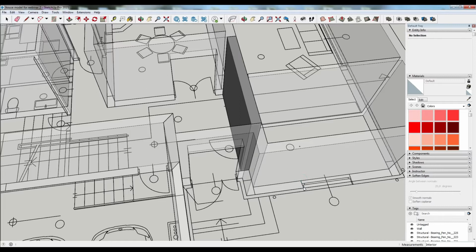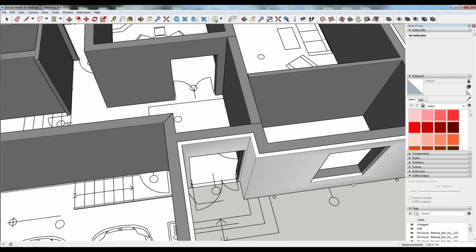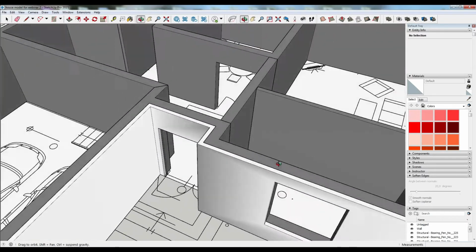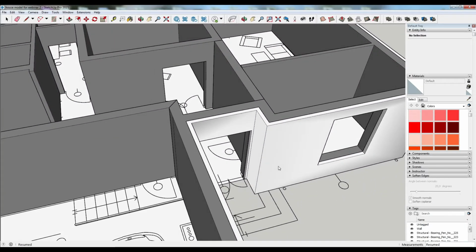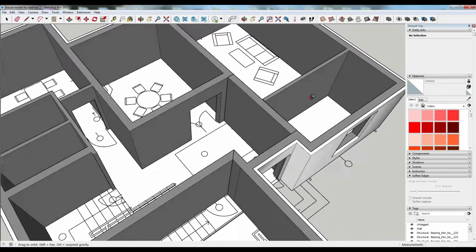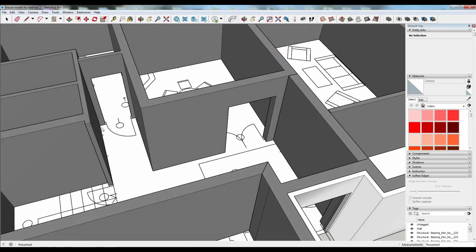I will show the starting point, but instead of clicking a second time on the end, I would give my number from the keyboard. And finishing with enter. As you may see, a window opening is automatically made. And you see that in this case we don't have to modify the group in order to finish the opening.